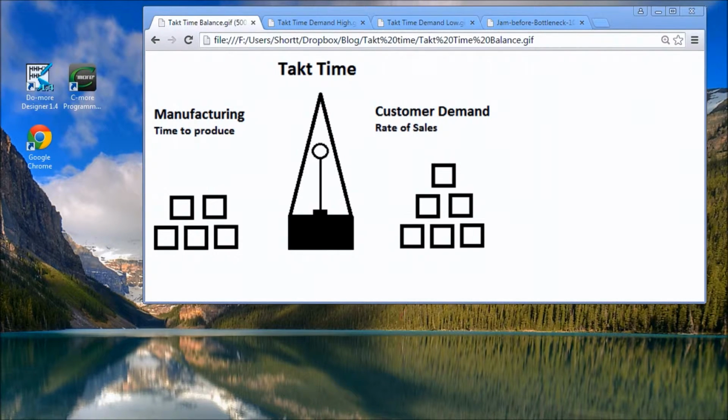Takt time is the total available time divided by the customer demand. The total available time is the time for the work to be performed, so you take lunch breaks and daily meeting times removed from that total time, unless you're constantly covering them by relief. Customer demand is the average rate at which your customers purchase products or service. It is expressed in the same time frame as your total time available. You can also project purchases from a customer in order to calculate this.